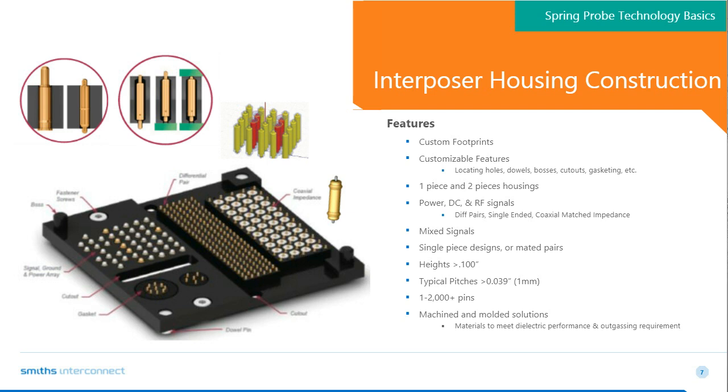Additional ways that you can also pass RF signals, especially in a ganged array approach, would be to utilize what we refer to as a standalone coaxial, where a probe is pressed into a standalone dielectric and then inserted typically into a metallized or grounded housing. In this image here is kind of what we're showing.